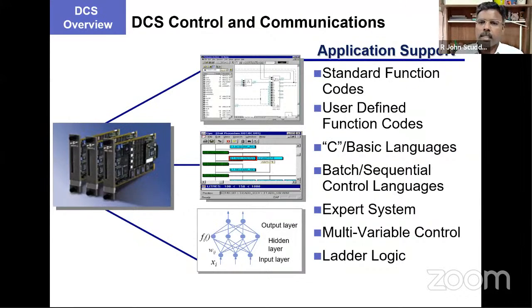In case after starting, the start feedback is not received, this software block, or the standard function block, will be capable of giving you an annunciation saying unsuccessful start. Or when you put it off, if there is no off feedback after a few seconds, or whatever time you have defined, then this block itself is capable of doing all that.